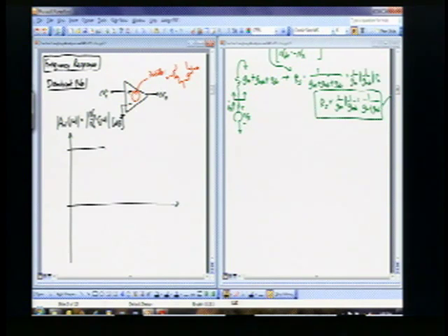Let me make that a little less steep so I can draw this a little better. So the slope of this thing here is going to be 20 dB per decade. But that might not be the only pole that it has. Right? That's its first pole there. But usually any of these circuits, if they use more than one transistor, is going to have many poles. And every time you have a pole at whatever pole frequency it has, it's going to increase the rate that this curve changes by another 20 dB per decade.